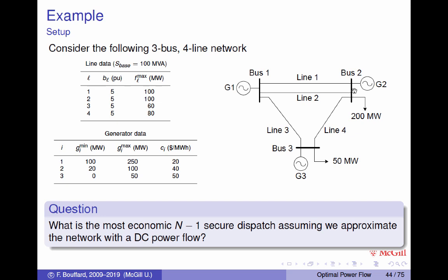So here we're going to have on line 3, that 1 megawatt going in, being taken out here, will go through 2 times the reactance going this way. So therefore the bulk of it is going to go here. So we're going to have 2/3 flowing in this direction and 1/3 flowing in this direction. But you see that if you inject 1 megawatt here and extract it there, it creates actually a counterflow of minus 1/3 in this direction.